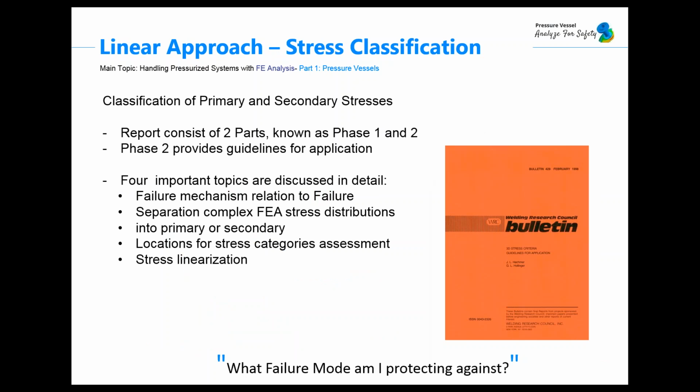The next question is how to properly classify the stresses, how to properly classify primary, secondary, membrane, bending. And what if the linearized stress result is ambiguous? These types of questions are very important, and FEA pressure vessel designers are usually facing them all the time.